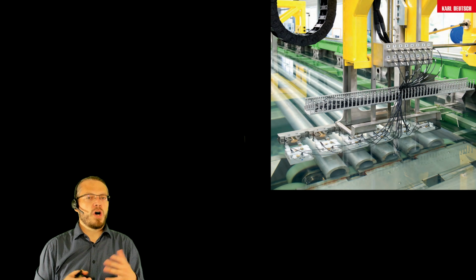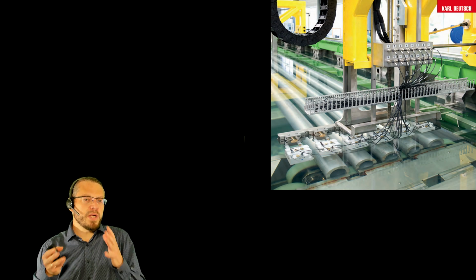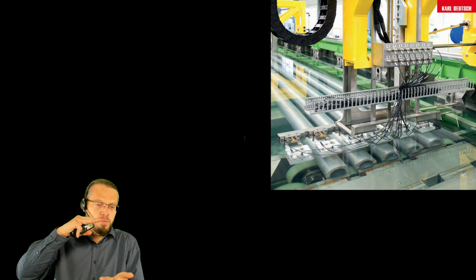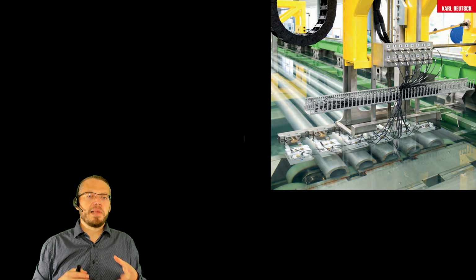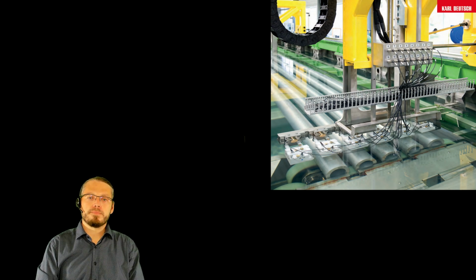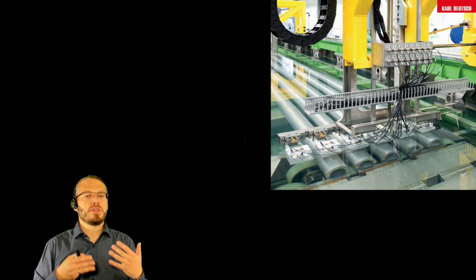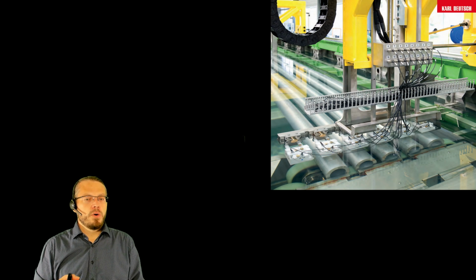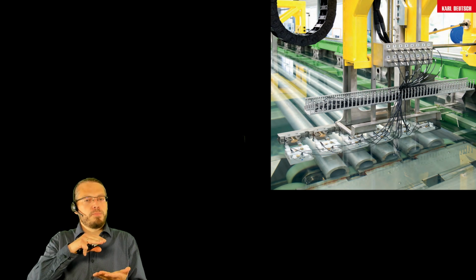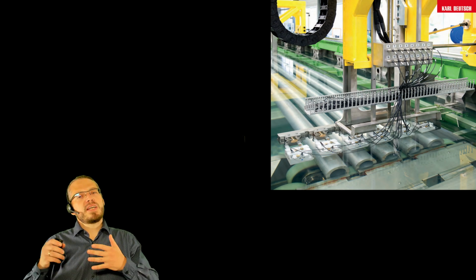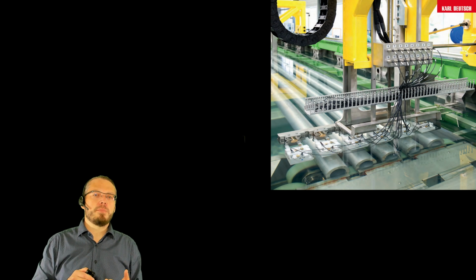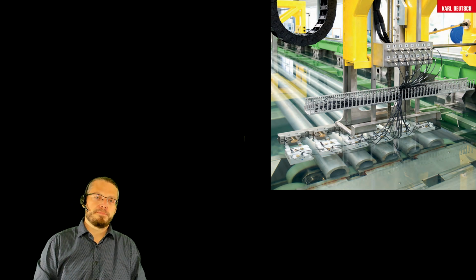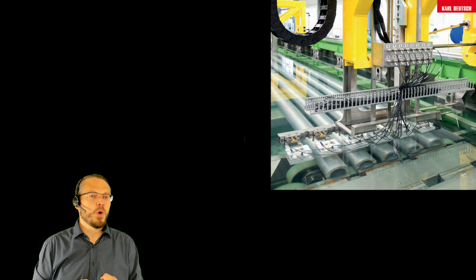And we talked about contact inspection, but instead of having the probe, a small gap of water, and then the component, we can actually put our complete component into the water and then do something called immersion testing. So we have a longer gap of water between our probe and our component, which makes some of the parameters easier to adapt and some of the parameters a little bit more complicated. Like we have to avoid air bubbles within the water.